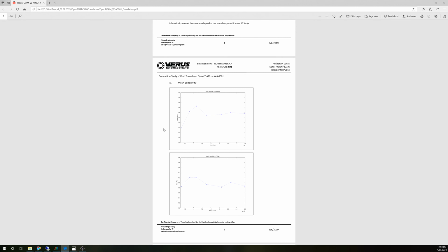So on car models with a lot of separation, say a dual element wing, big diffuser tunnels and a front splitter, we do things a little bit differently with our mesh to make sure we're capturing stuff properly, based on what we learned in the wind tunnel.